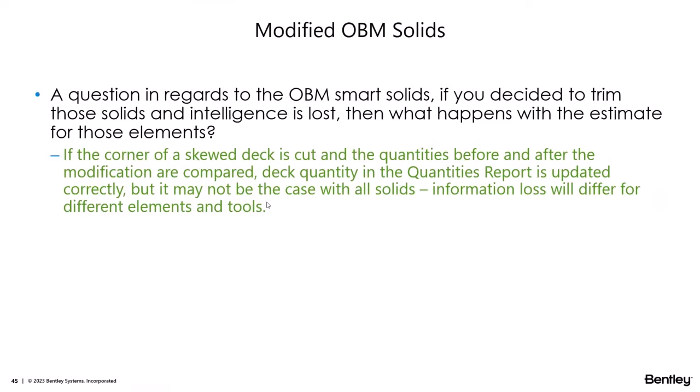They've honored any of those manual changes that have been made. But be forewarned, if you do some deck breakbacks by hand, and then go back and modify some variables on your deck template, it's going to delete and redraw that deck, and it's not going to be aware of any clipping that you had done to that model after the fact.